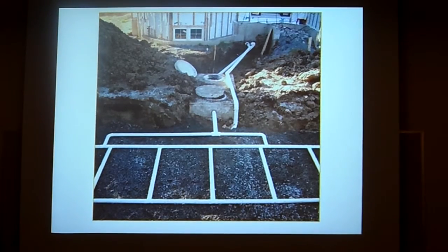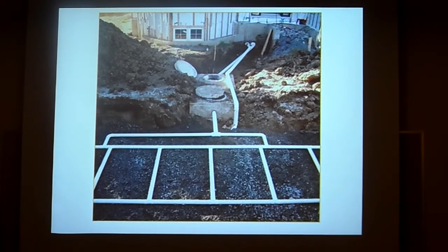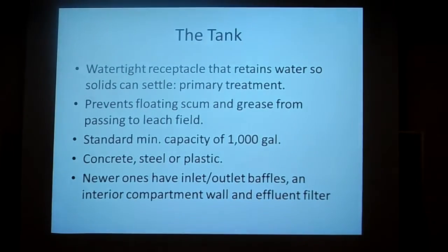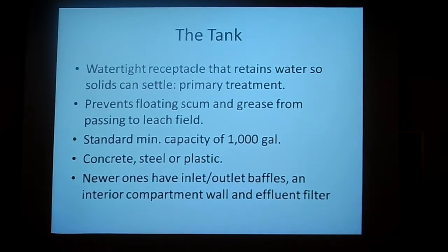And this is what they would look like in real life. At the bottom of the screen, you can see the leaching system is filled in with gravel or stone material to improve drainage. The tank itself is a watertight receptacle that retains the water so that the solids can settle, essentially primary treatment. These tanks are designed to prevent floating scum and grease from passing to the leach field.